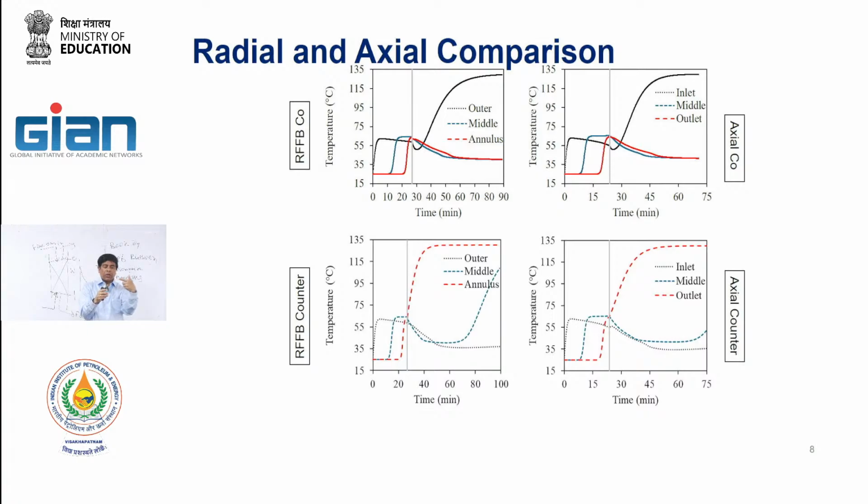The other issue that comes there is because of the flipping of the direction for co-current and counter-current, it's very tricky how you start the desorption. Because you start the adsorption and then you are saying the flow is not in this direction, the flow is in this direction. So the sign of the velocity changes. Anybody who works in CFD is very well aware of it. A typical CFD simulator can handle the change of sign of the velocity. It is very difficult to do this in Aspen or any other simulator because it will change from plus to minus.